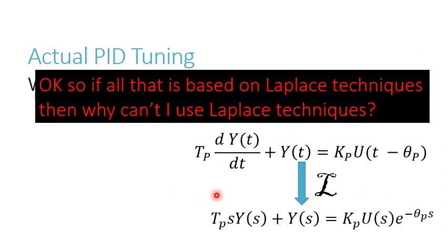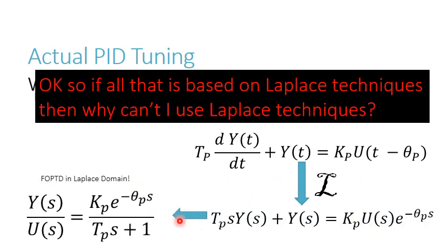Okay, well, let's try to take this into the Laplace domain and see what happens here. I just took the Laplace transform of this first order plus time delay differential equation, and then let's rearrange it. And here you go. So this might be familiar to you if you've taken EC 460 or some control courses. This is your Laplace domain first order plus time delay model.